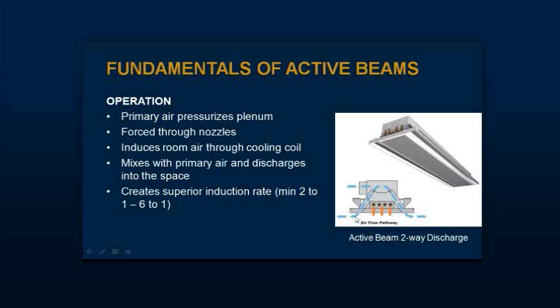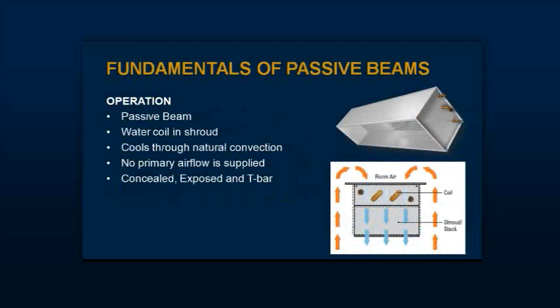This, in turn, causes a low pressure center to form here above the coil, and then draw room air up through the coil, mixing it with the supply air and entering the room as a mixed media of recirculated air and primary air inside the space. And this is an incredibly effective way of taking localized recirculation and achieving a high level of sensible heat transfer inside the space, both heating and cooling. Again, for more information on this topic, I would refer you to one of our webinars.